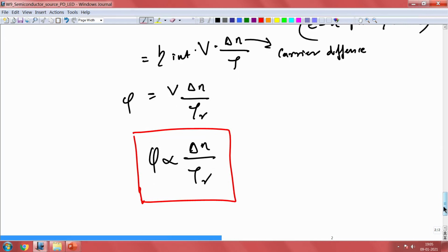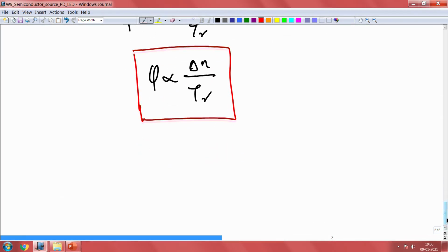Okay. So, how do we achieve this scenario? So, your recombination rate is intrinsic to the material, but then you can play with this injection. So, the injection or the current, the carriers that you have, can be increased by putting more current into the system, but you cannot increase the current as you like, because there is a limit to the material itself. So, it will break down because you do not have many carriers to flow through, but you can increase the density of carriers. So, that is something that you can do, right.